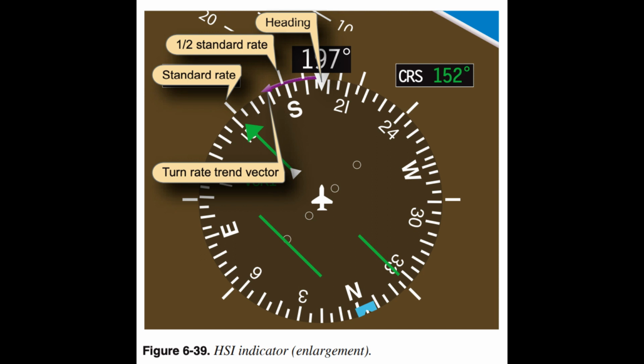With the introduction of airspeed tapes, the pilot can monitor airspeed to within 1 knot. Fixation can lead to attempting to keep the airspeed to an unnecessarily tight tolerance. There is no need to hold airspeed to within 1 knot. The Instrument Rating Practical Test Standards (PTS) allows greater latitude.